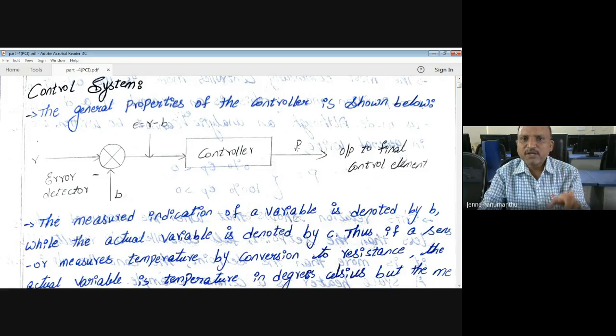Either it is open or it is completely closed. So that type of control action is the so-called discontinuous controller mode. So here in this diagram, P is completely open for such an input or completely closed for other inputs. That's the meaning of this control action.